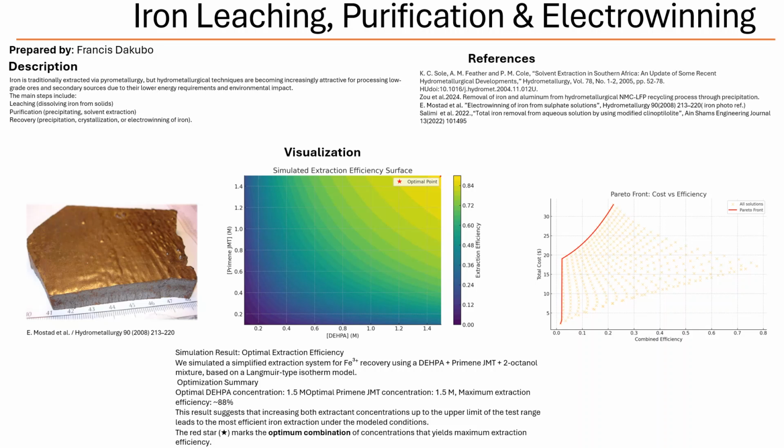Okay, so how do you even begin to tackle that kind of problem? Well, the researchers in one of the articles came up with a clever approach. They used what's called the discretization method. Instead of dealing with the process as a continuous flow, they broke it down into smaller chunks of time. Time segments. Exactly. And they focused on the control variables, those being the rates at which oxygen and zinc oxide are being added. Within each time segment, they treated those rates as constant values. So it's like taking a series of snapshots of the process at different points in time. Yes, that simplifies things a lot. It turns the continuous problem into a nonlinear mathematical programming problem that can be solved with computers.